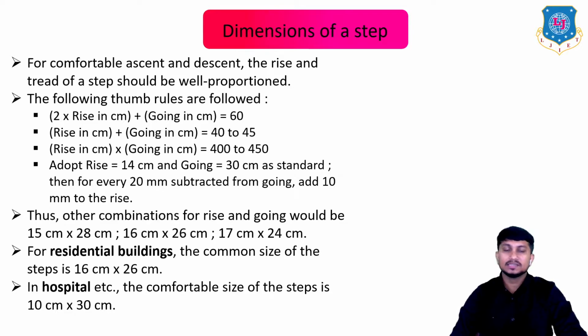For residential buildings, the common size of the steps should be around 16 centimeter by 26 centimeter. In hospitals, a comfortable size of steps should be provided, and it should be around 10 centimeter by 30 centimeter. Here, the rise is comparatively lower than in residential buildings.